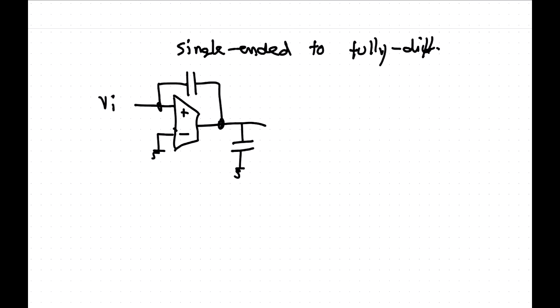So V in here, and then we have the load sitting here. Now, it is required, for the easiest way, that all your transconductors have one input to ground. Often they do, but in the inductor we used before, not all of them had one input to ground, in which case you need a differential type of transconductor.